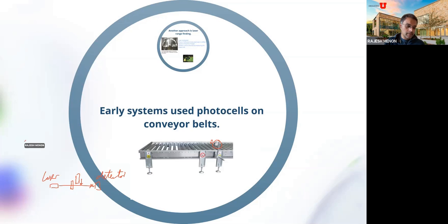So there's a peak signal, suddenly it drops a little bit, and the length of this drop in terms of time, if you multiply it by the velocity of the conveyor belt, will give you the actual length of this bottle, right? And of course, you can imagine different orientations to ensure that you get different shapes in X and Y and potentially in Z as well. And then doing some image processing techniques or data processing techniques, in this case, not an image, to be able to detect the shape. By the way, this is also what's done in garage door openers, as many of you might know.